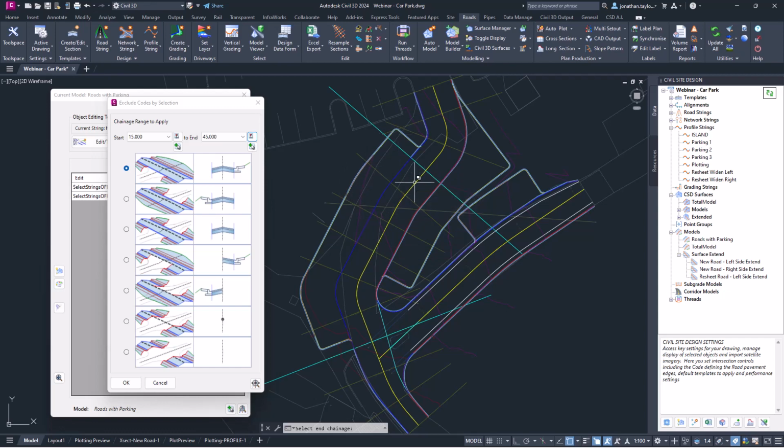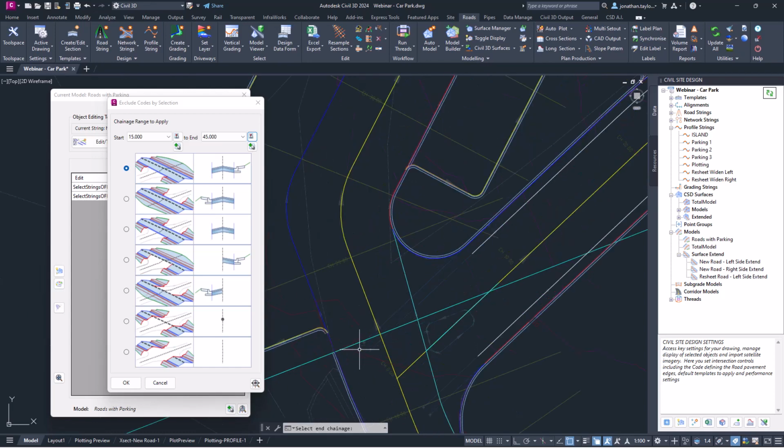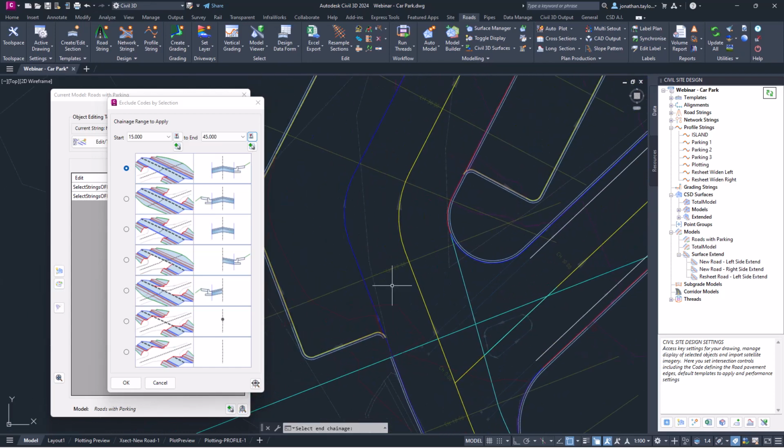Well, for this road I've got sort of 5 meter spacings, which is why the software is jumping to the closest spacing or closest sample line that's available. So what we need is sample lines at the particular point where we want to cut, and it's very easy to do. All you do is use this button to add them in.